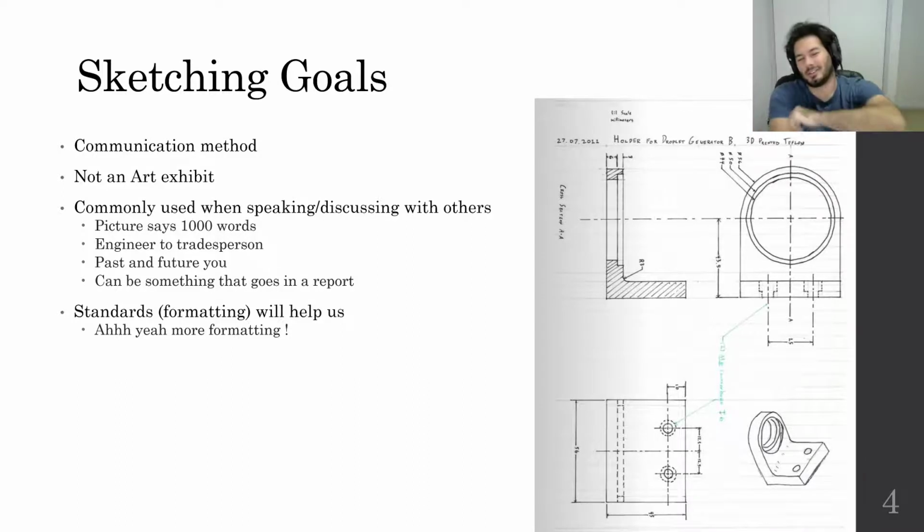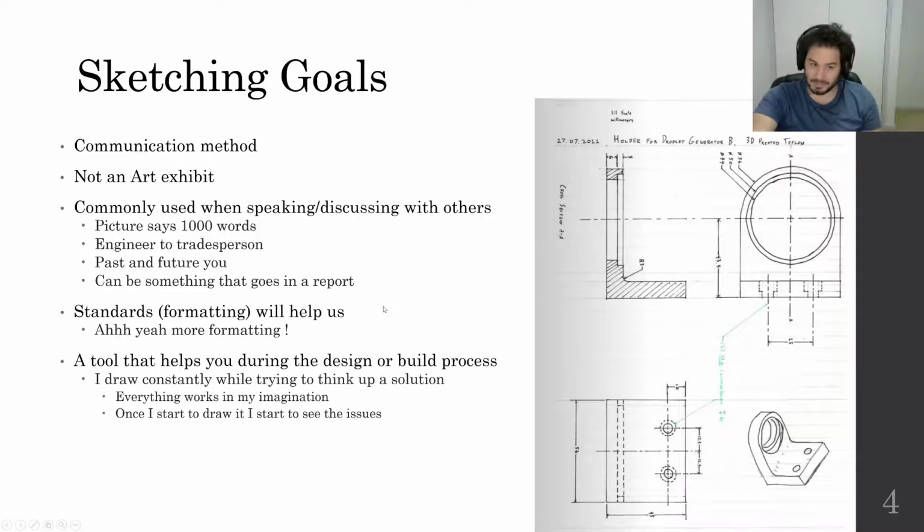As always, formatting rules, because formatting rules are the best. We're going to talk about these for a little while a bit later on in this presentation. Whole bunch of formatting rules when it comes to engineering drawings around things like line styles. So just as a one-off quick one, this long, short type of line here, this is what we call a center line, and it denotes to me that that's the center of a circle. So even though this guy maybe didn't draw a perfect circle freehand, he gave me center lines, I know what's going on, that makes sense to me. So there's all these rules around how you format things that help you communicate information, which is generally our number one goal, right? And it helps us not have to be artistically brilliant if we use the formatting to help us.